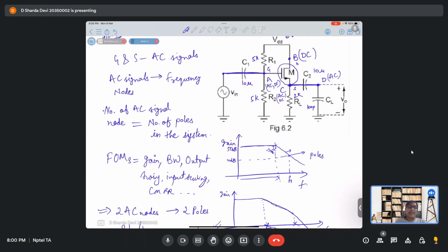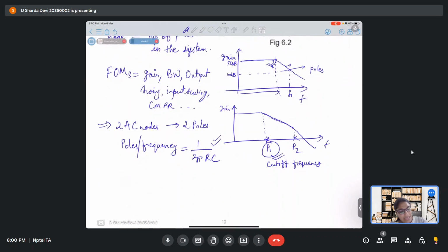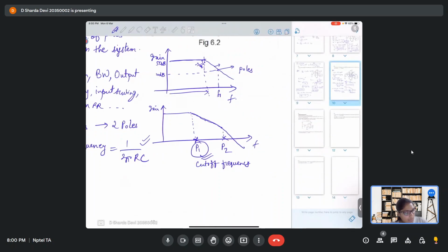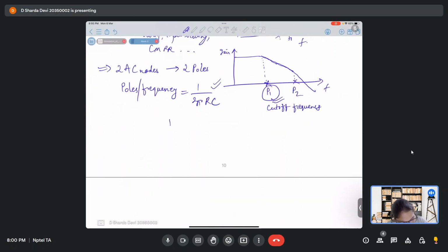So you will see some other capacitances. Now what are those capacitances? These are intrinsic capacitances to the MOSFET. Okay. So let's see what are the different capacitances that we have in a MOSFET. So when there is this MOSFET with gate, drain, gate, source, and there is another which is body, each and every terminal combined with one another, they have capacitances, okay, because they get coupled with one another. One terminal gets coupled with another.